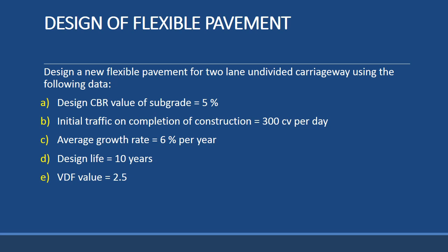In that chart we will be able to find the total thickness of the pavement. After that, we are going to see another catalog, the catalog for design of pavements, given for different traffic ranges, and in it we will find the thickness of each layer. I will show you that later.